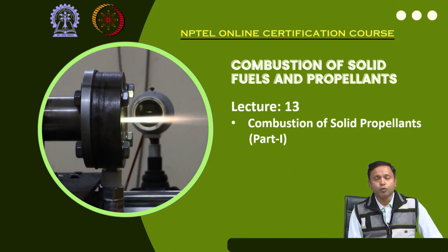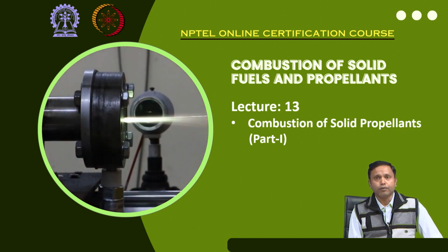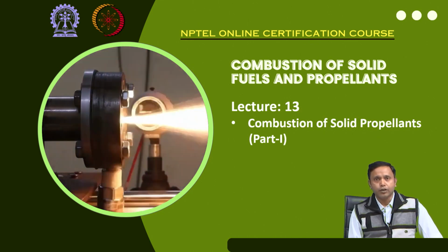For example, homogeneous propellant or double base propellant. Then we talked about the heterogeneous propellant or composite propellant. We have also talked about the modification of double base propellant, like composite modified double base, by adding some ammonium perchlorate or even nitramine oxidizers. And then we also talked about a separate category, nitramine propellants. So what we have learned there is that depending on the ingredients, the characteristics of the propellants will change.